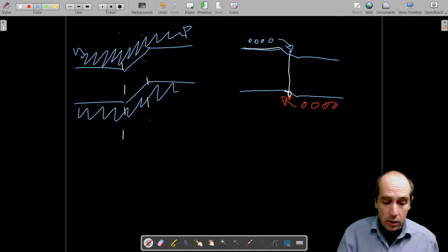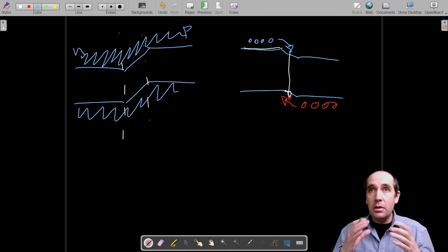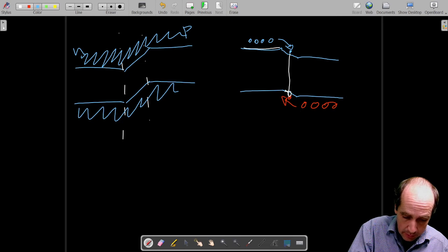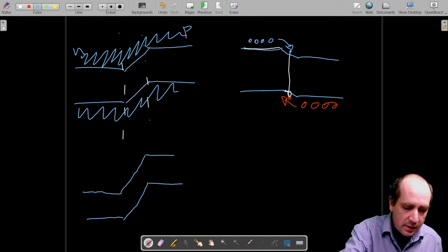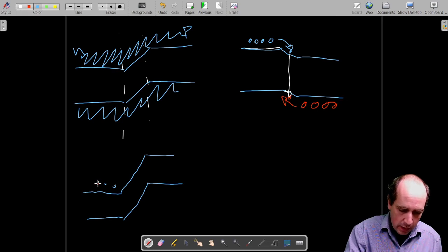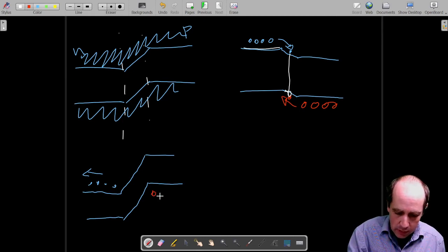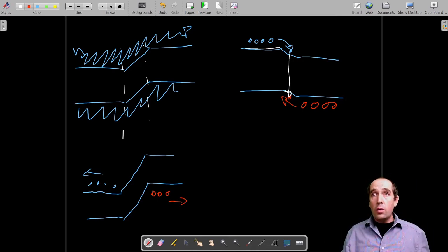So the opposite scenario is now that the bias is in the opposite direction, and now the misalignment of the bands occurs in reverse, and so if anything, now this slope will be bigger. This jump between the energy on one side and the other of the junction means that now electrons over here are being pulled away from the junction, and the holes over here are also pulled away from the junction, and since the junction has no carriers, there will be no conduction.